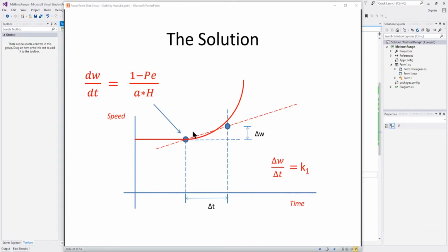So in the previous video, and I strongly recommend you take a look at that so you can understand the basic concepts behind what's required to solve this, we talked about how the response of a generator, the speed and the acceleration of a generator, is dependent upon the difference between the mechanical power input to the generator, mechanical power into the turbine, versus the electrical power out of the generator. If the electrical power out is equal to the mechanical power in, then there is no change in speed. And this equation here we saw in the first video describes that.